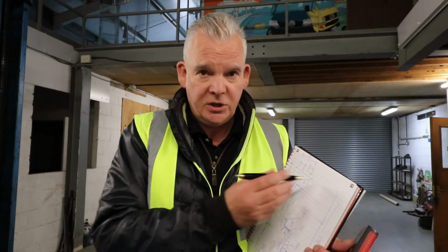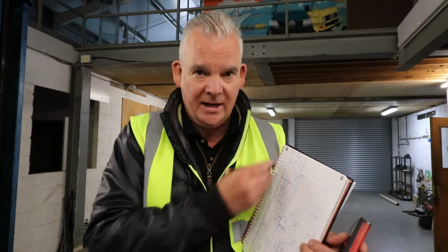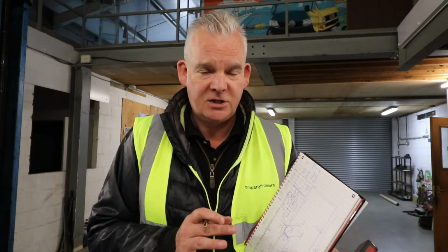We can always double check those measurements, but we've always got to make sure that the building itself is right. Don't start with all the internal measurements and hope that they will all work out. Always check those ones first. Triangulate, go sideways to sideways just to check that everything is square.